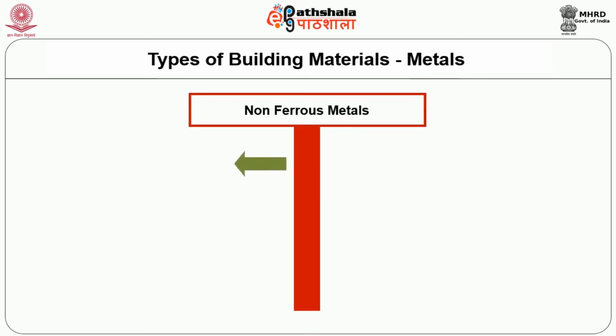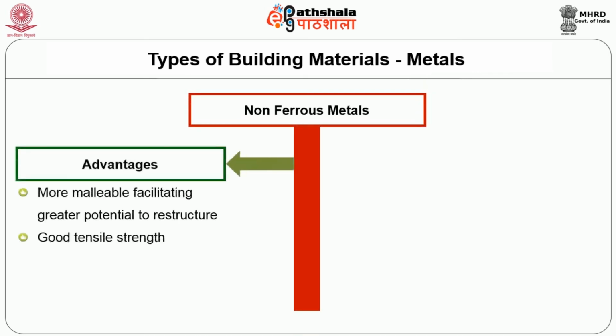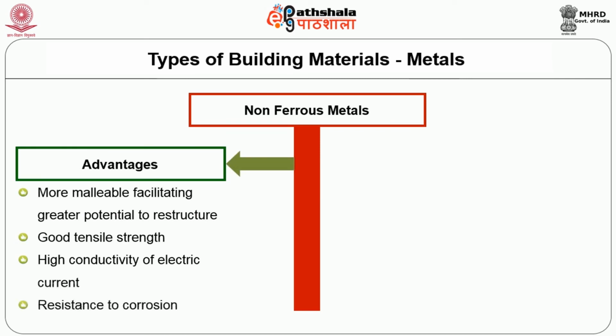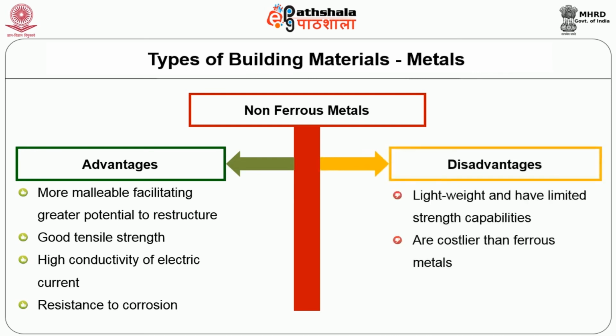Non-ferrous metals have the advantages that they are more malleable, facilitating greater potential to restructure, with good tensile strength, high conductivity of electric current, and resistance to corrosion. The disadvantages are they are lightweight and have limited strength capabilities. They are costlier than ferrous metals.